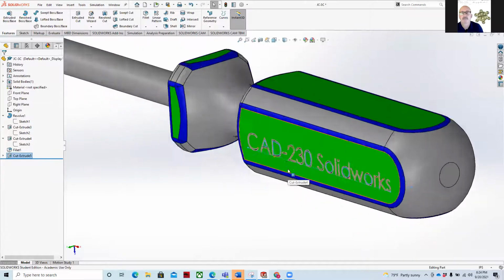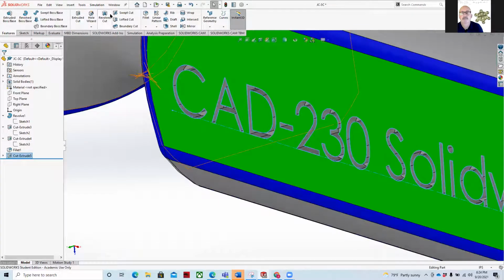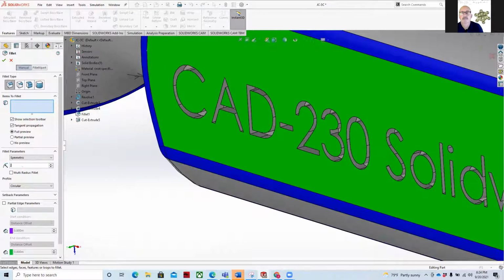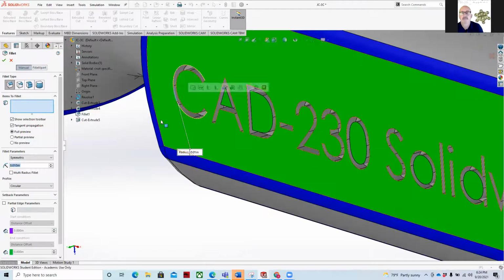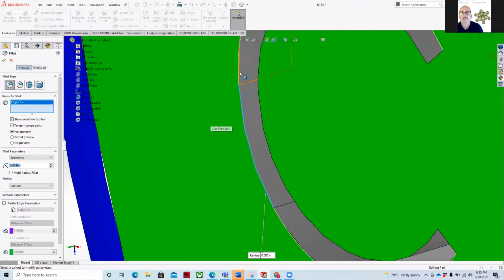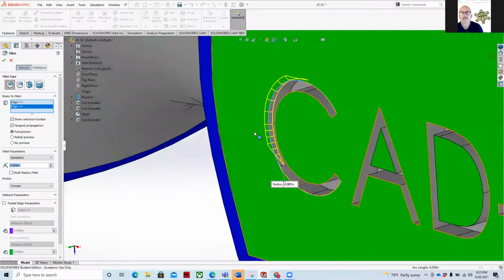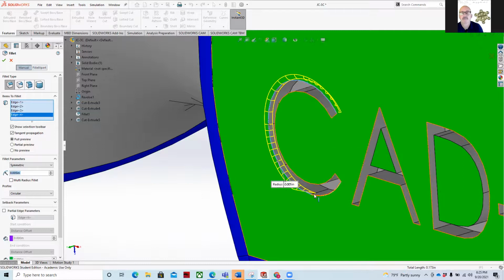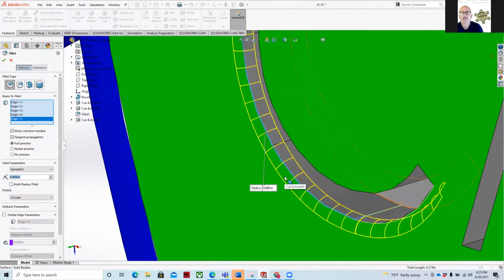You can do more with this if you want to. You can add fillets to it. So if you wanted to get something a little softer, you can get a very fine fillet. Let's go with 0.010, 10 thousandths. It might not be enough to do it. I think it's too small. 0.005. So I'm kind of pushing it a little bit here, but it depends on what you're into, how far you want to take your design elements.